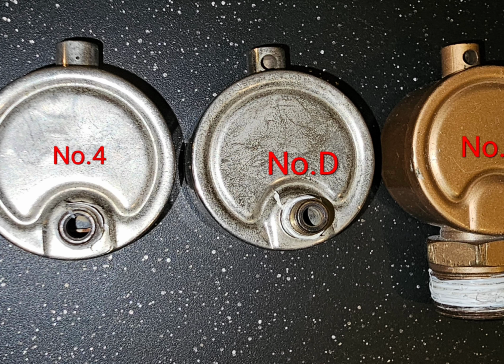What you'll notice about a steel convector, one of its advantages, is that it heats up excessively fast. If all you have in your heating system are steel convectors, guess what? Your boiler is going to build up pressure fast. She's going to reach her cutout. She's going to shut down. She's going to kick back on when they cut in, and she's going to continue to repeat this process until the call for heat has been satisfied.